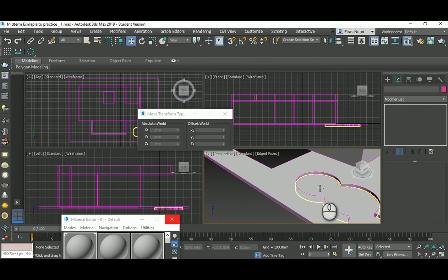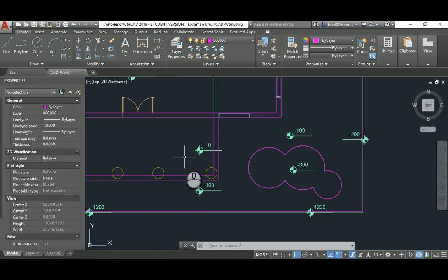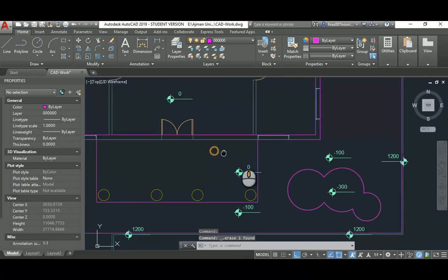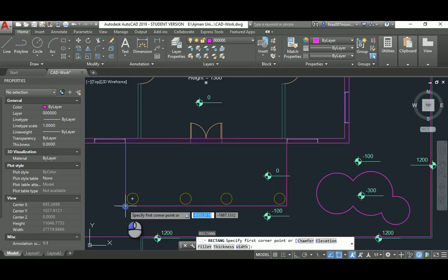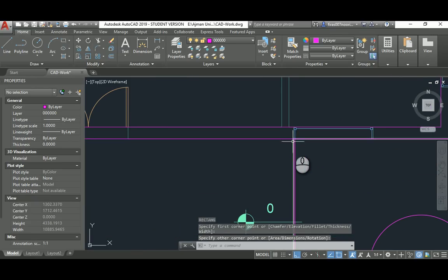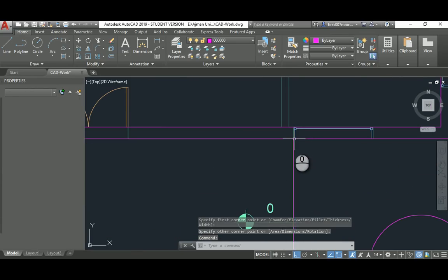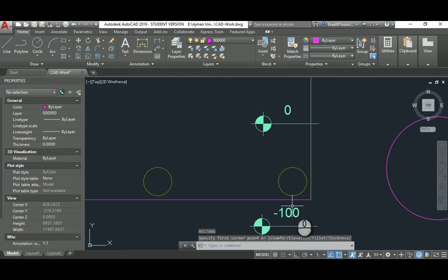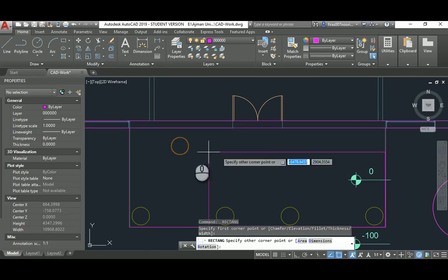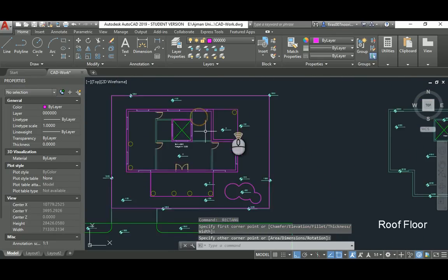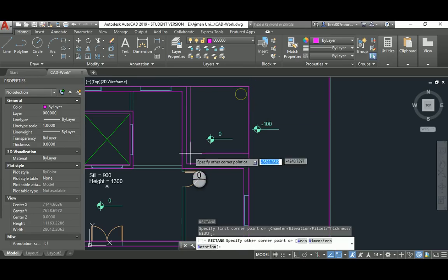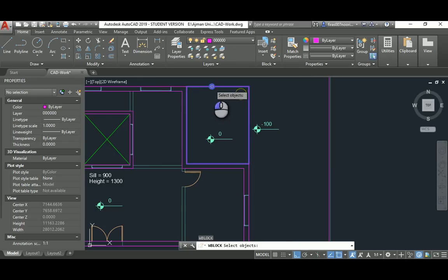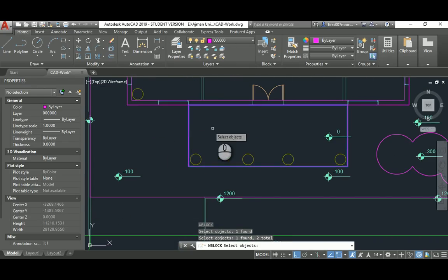You get this, okay? Now both this slab, I'm just gonna remove those, it's just kind of annoying. I'm just gonna take this guy, oops, I'm deleting it, just rectangle, okay, and I'm gonna take this guy, just right block and select this one, and they are located on a level of 0.